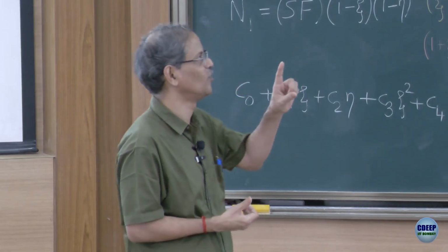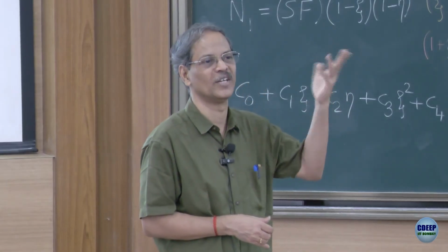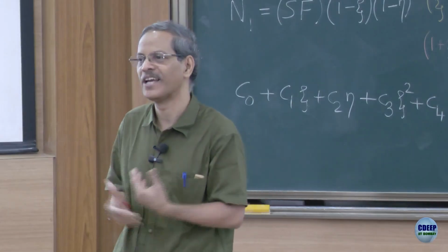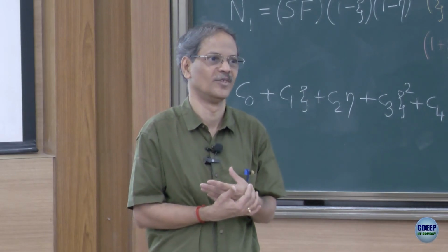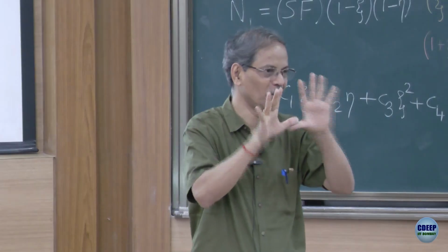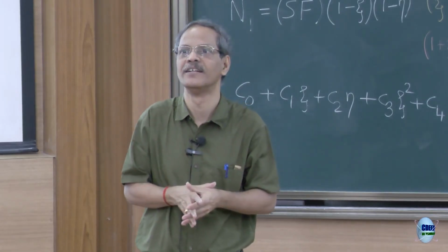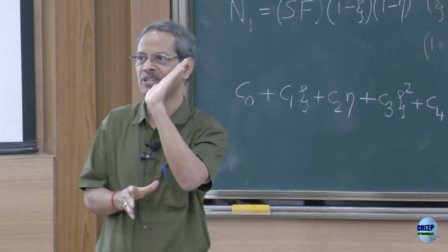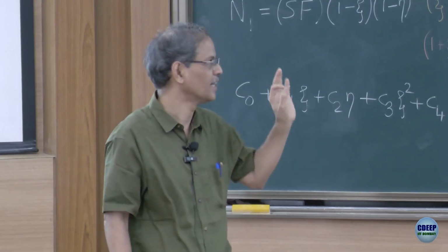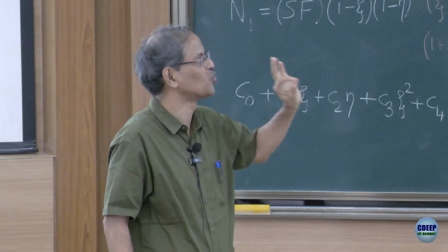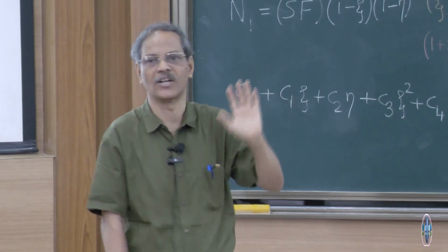So, x6, y6 will be (x2 plus x3) by 2, (y2 plus y3) by 2 basically. Then what would I get? Without doing anything, without putting your pen on paper, what do you think you would get? Huh? I mean, one edge would become a straight edge again. Is that much clear? If I were to take x6, y6 to be the midpoint of 2 and 3, I would be reducing this to a straight line.